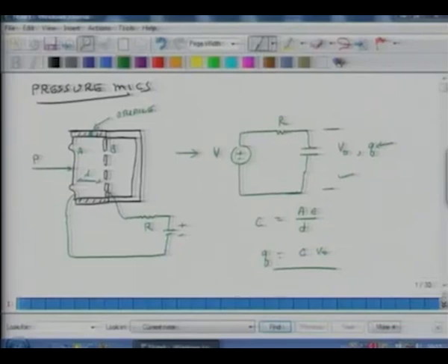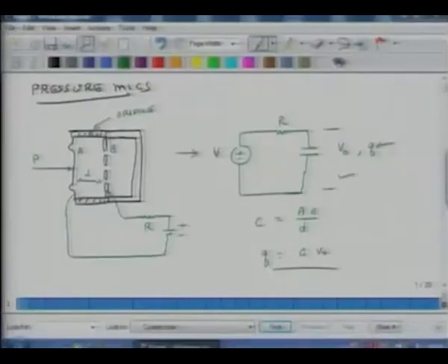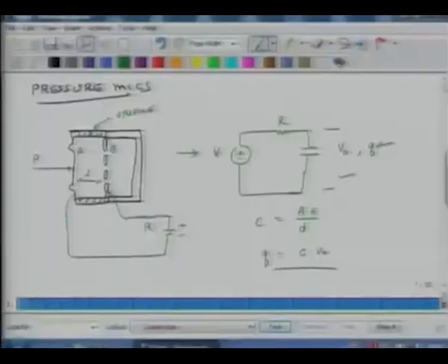Someone may ask, why do I have this surface be slotted? The essential reason is that there could be some frequencies which may excite the resonance of surface B, so then it does not behave in a very controlled way. What the perforations do is act as acoustic resistors. So when you are developing the acoustic circuit, you have to include that resistive element. And what that resistance does is damp out the vibrations. So this is a capacitor microphone.